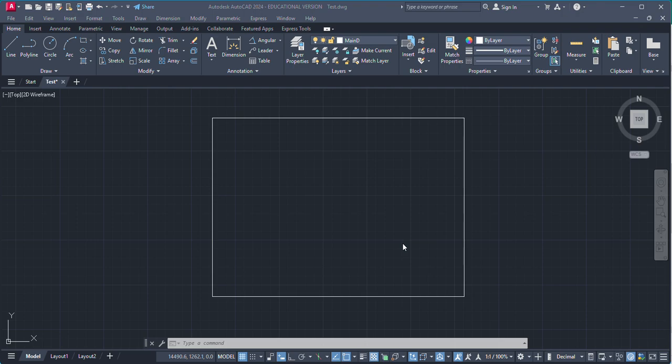Hello everyone, welcome back. In this lecture, we will talk about isometric projection. We will learn how to draw isometric projection in this 2D sheet as well as in isometric drafting. What we have learned till now is orthographic projection, in which we have to project a 3D object in this 2D plane with the help of two dimensions.